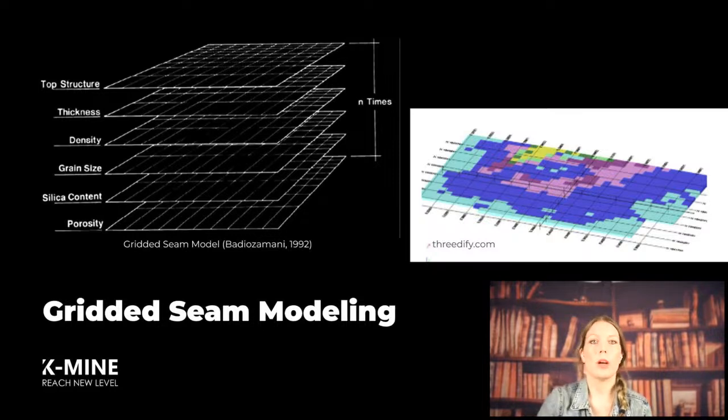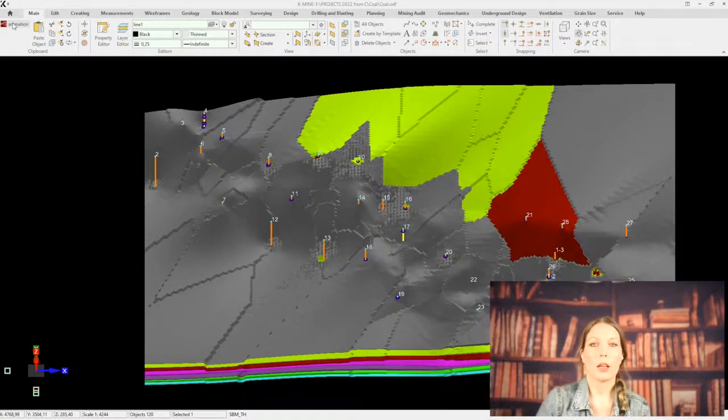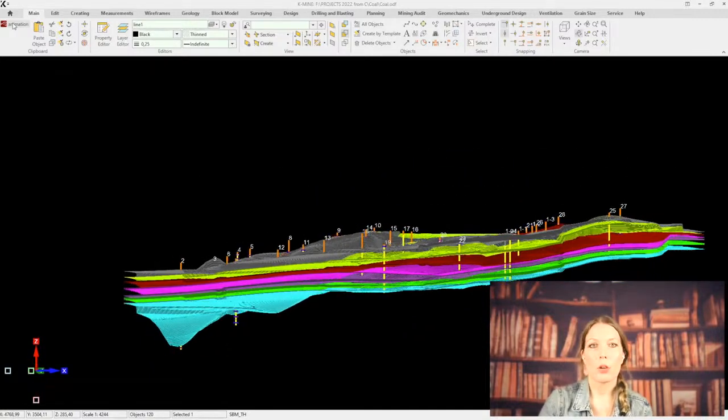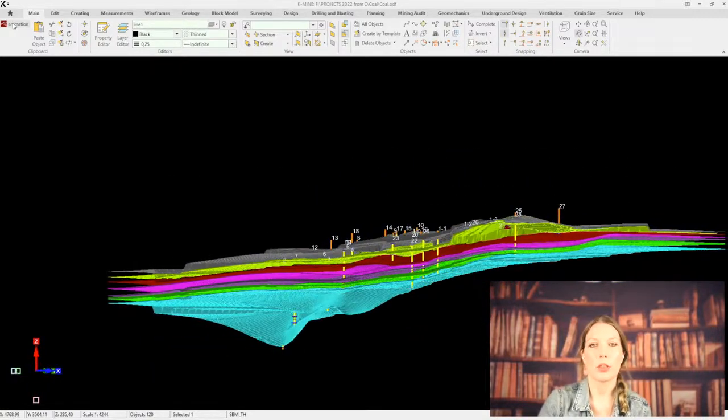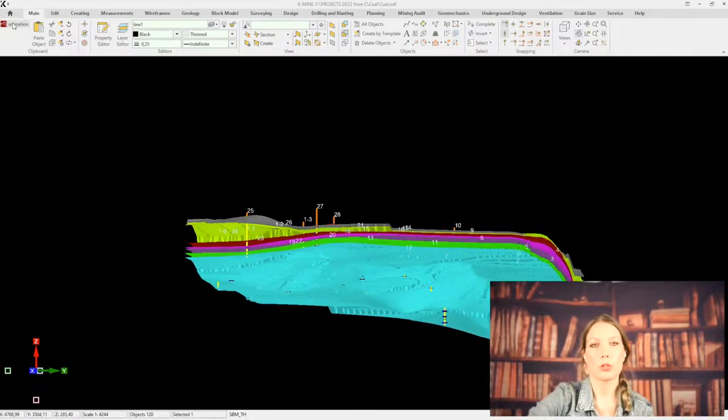As a result, bed surfaces emerge from interpolating a collection of unevenly spaced data points into a uniform fixed matrix known as a grid. The specific interpolation technique used within the grid can vary depending on the software in question. These methods are tailored for seam deposits like coal seams, thin phosphate layers, or limestone beds where the horizontal spread far exceeds the vertical thickness, posing computational hurdles for traditional 3D block modeling approaches.